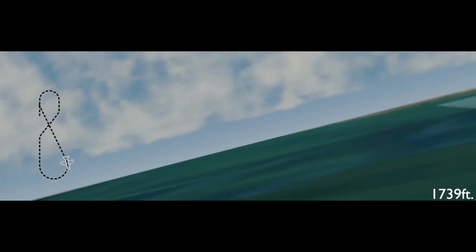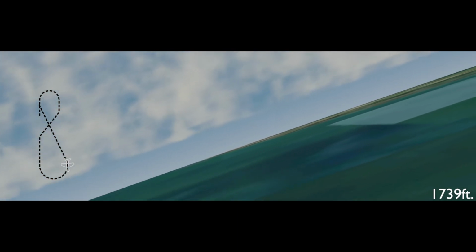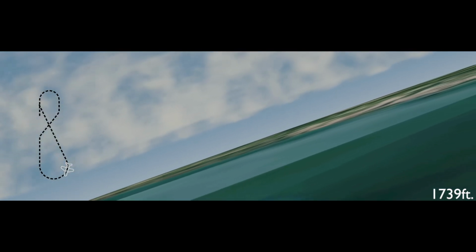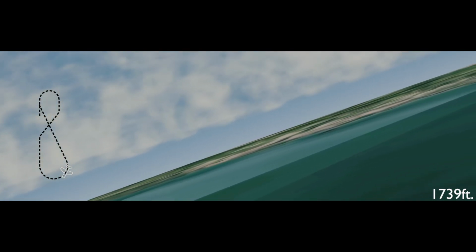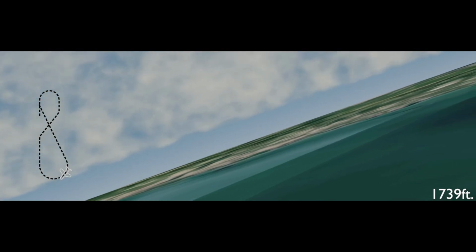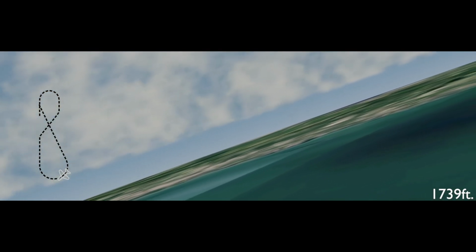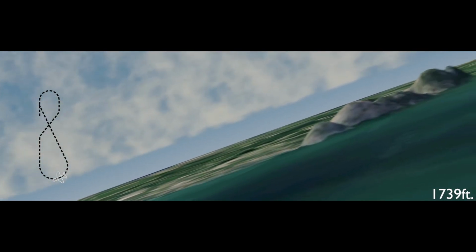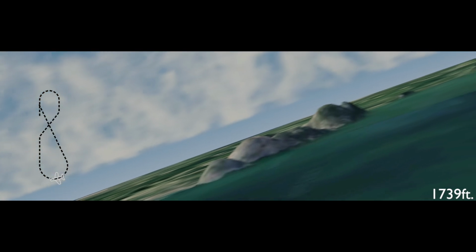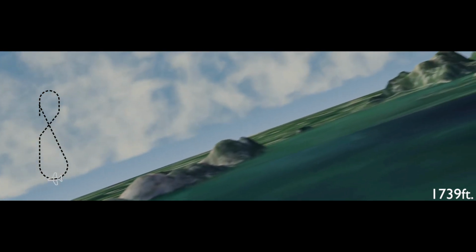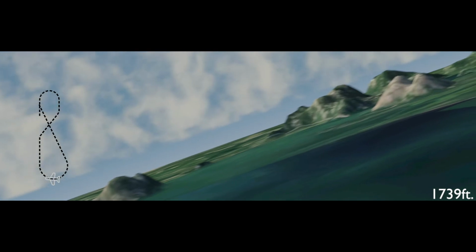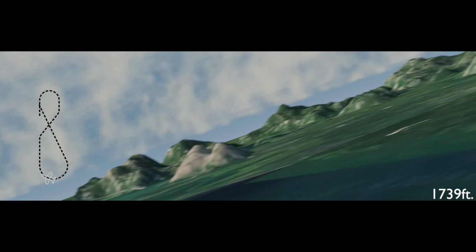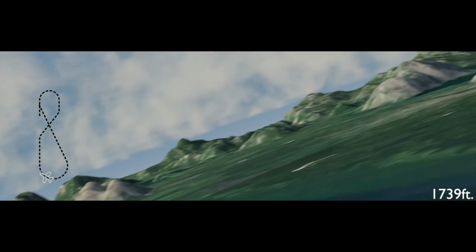Now we're starting the base turn for the ILS procedure at 1,740 feet. In this example, we're flying the instrument final approach at 150 knots. It's a 3.2 degree glide slope, the wind's calm, the temperature's around ISA, so we've calculated the required rate of descent is 850 feet per minute. To achieve our continuous descent final approach, we're going to establish an intermediate approach configuration before the final approach fix, and then maintain that configuration during the descent on the instrument final approach.